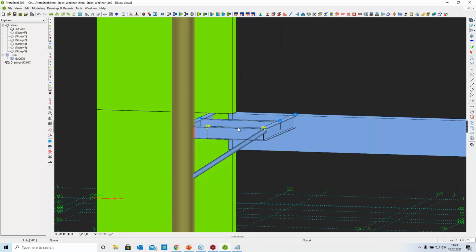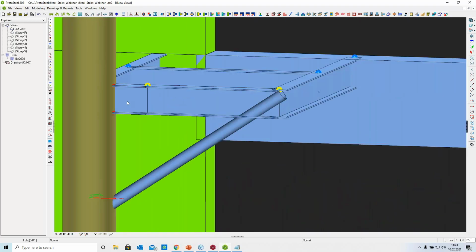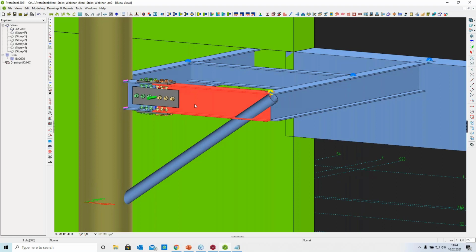So Mr. Çağlar also split these beams, so I will connect them with a splice connection. Let's select the splice connection and select these beams in the 3D view, and the splice will be generated here. And the next thing might be, for example, these secondary beam connections.